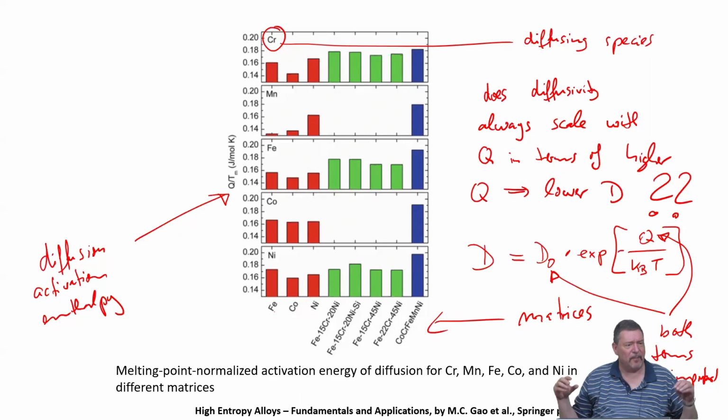So it means the process of the jump is quite large, but the vacancy will always be closely by. So the probability of finding an empty space is then very large. And this can then give rise to these counterintuitive relationships of having higher diffusivity even though the activation barrier is higher.